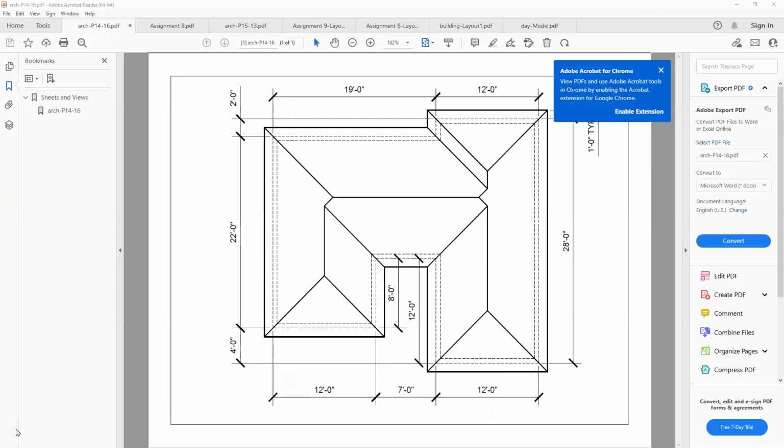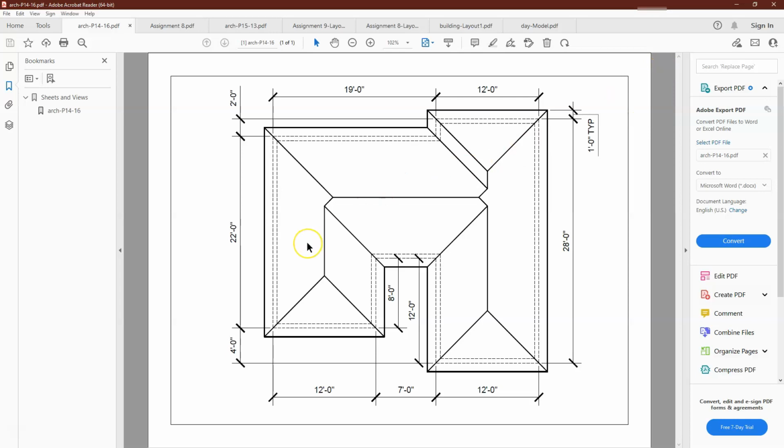Okay, so now when I open up the PDF, I notice that it is multiple PDFs, so it's not going to group it as one if you have multiple layout and model tabs. So that's something interesting that I find out. So it's probably best to choose either one or the other option. Either print all of your layouts and it'll group it into one tab, or if you group all of your model spaces and it'll group it into one tab.